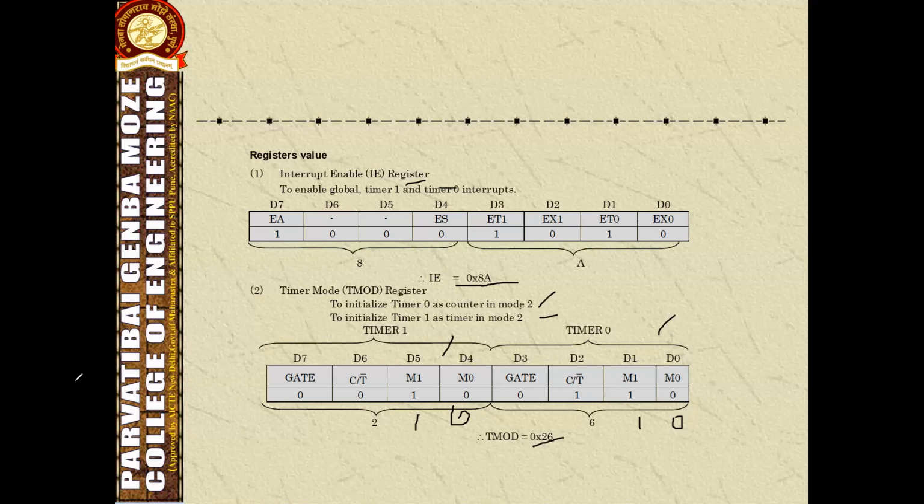Timer 0 will count the number of pulses on the T0 pin. Hence, it is initialized to 0xFF, so that whenever it overflows it will cause an interrupt and hence increment the count. Since it is in mode 2, the count FF will be loaded into it. So when TL equals FF and TH equals FF, it reaches the maximum value.